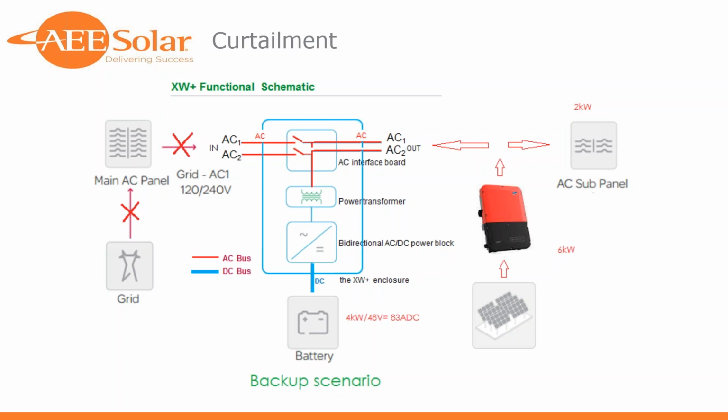B, they probably didn't have enough battery. They had uncontrolled charge currents. They didn't have a way of curtailing the PV inverter. Their hearts were in the right places, but it was really not the right application. The best thing to do from the get-go probably would have been to install a high voltage charge controller, so that they could still get full array power, but that the battery inverter could tell the charge controllers how much to harvest and how much not to harvest.